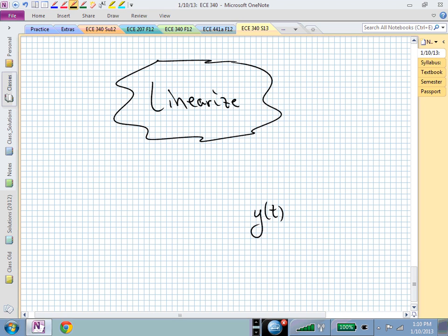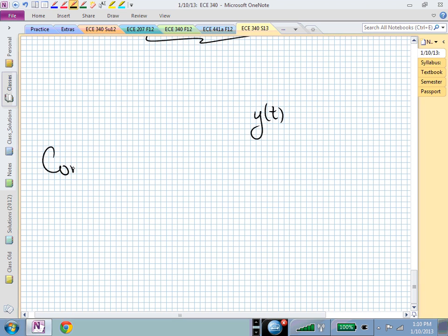We'll do that in this class all the time. That's what we want to get comfortable with: we start in the time domain. Oh, I want to work in the frequency domain. It's easier because I can now multiply. I don't have to do this convolution integral. But we want to be comfortable with both. If we did convolution, if we stayed in the time domain, then y of t is now this integral from minus infinity to infinity of, let's say, h of tau, x of t minus tau, d tau. That's all in the time domain.